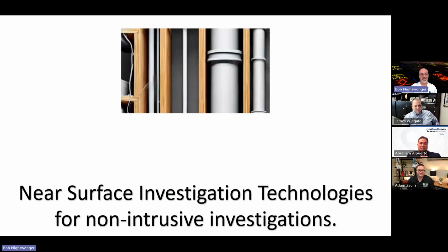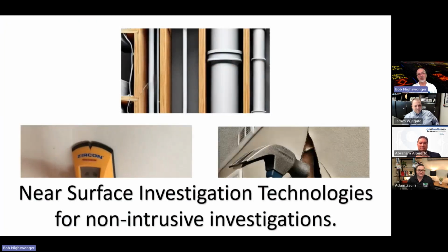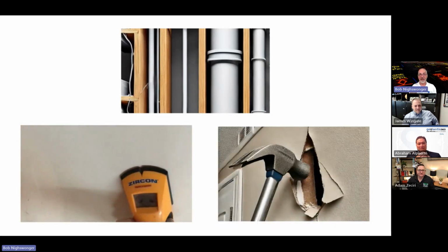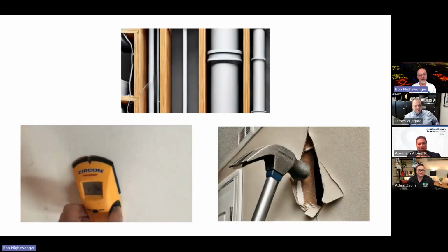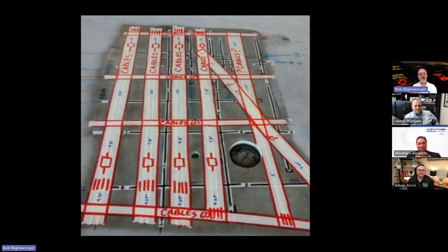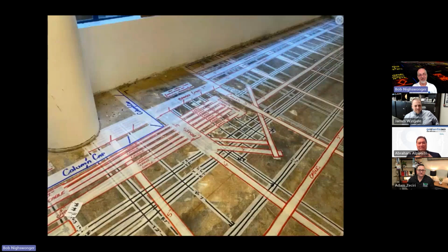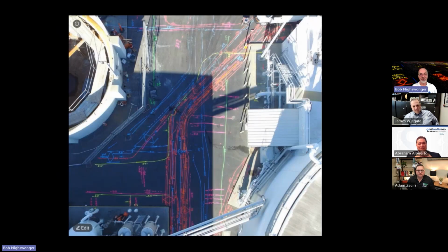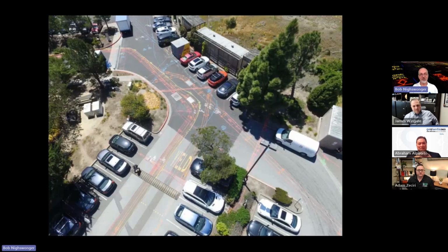We're all on the same side. Now, there isn't a single source that can locate an underground line except for maybe a vac truck or a backhoe or a trencher or an auger. Electronically, we're not marking the line. We're marking what we assume to be top dead center of the line. So if we can map our signals, and that's what we're doing, is mapping our signals. If we get an extra line put in close to us, the next time we locate that line, our signals might be a little skewed, might pull towards that new line that was just put in a foot or two from us.